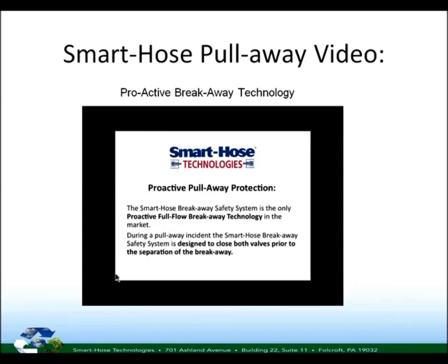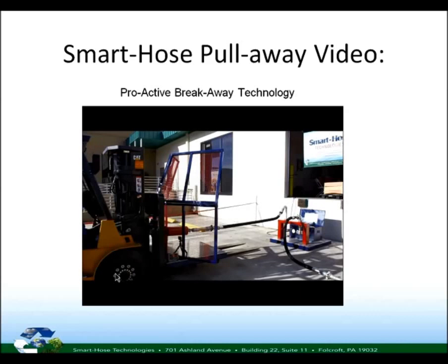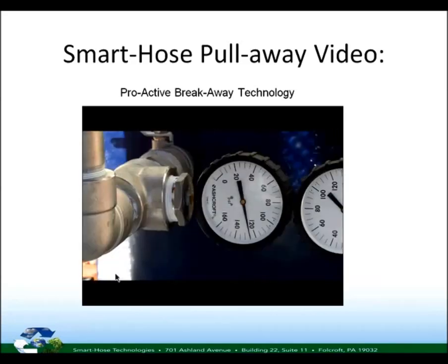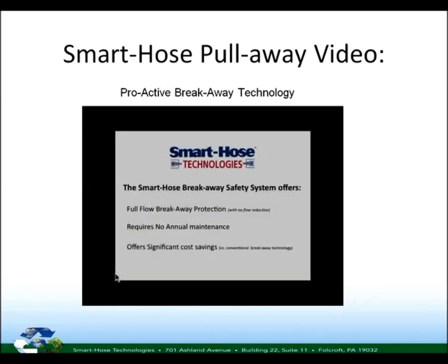Now the second one is an actual breakaway, and we're breaking it at a 45-degree angle. We pressurized it with 120 psi, just shop air. It pulls back, and he breaks it. That pull force was about 840 pounds, and it's just us showing that it still held pressure.